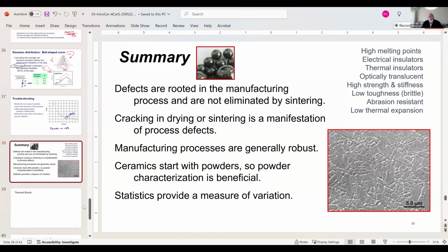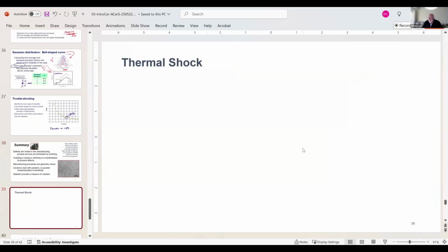Okay. So, thermal shock. This guy, Hasselman, used to be thermal shock was that you would have a delta T that led to failure. Okay. And Hasselman, who was a really famous theoretical mechanics guy, he said, no, it's not. It's actually the concept of damage.